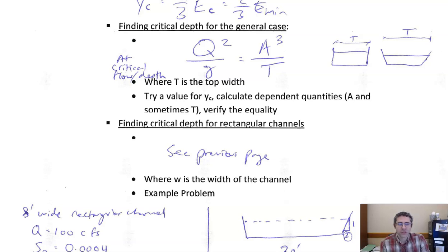And so how do we actually solve using this? Where does the critical depth actually show up? Well, the critical depth shows up usually in the equation for the cross-sectional area. If this was a rectangular channel, A could be written as B times Y, and then you could solve for Y. In that case, T in a rectangular channel is also equal to B, so that's helpful.